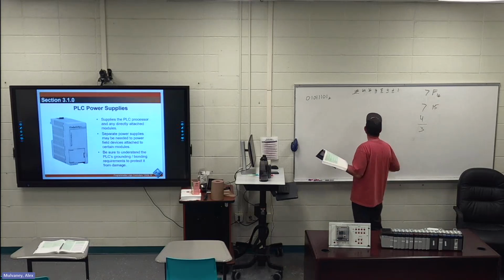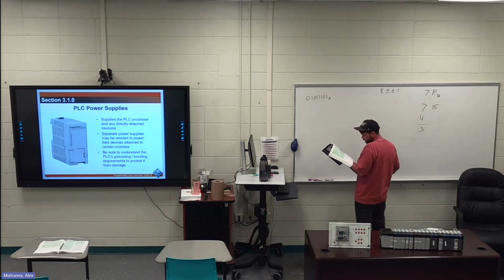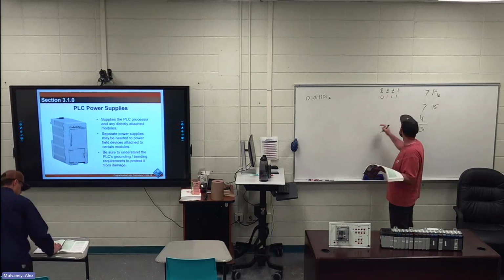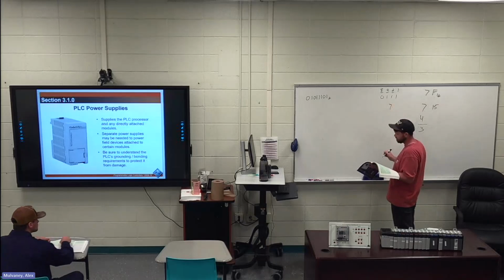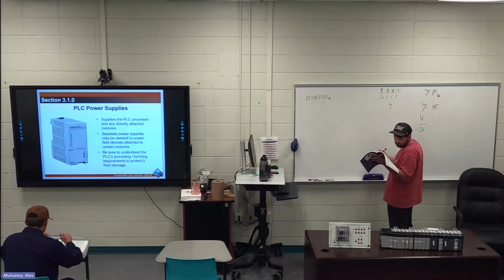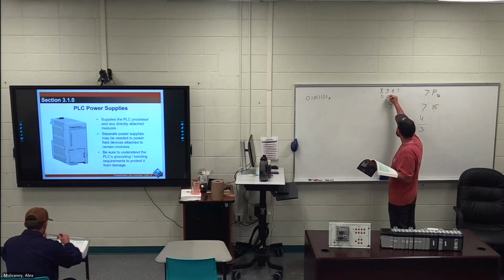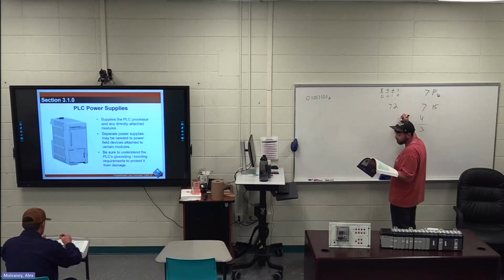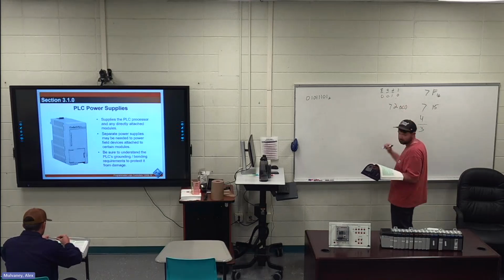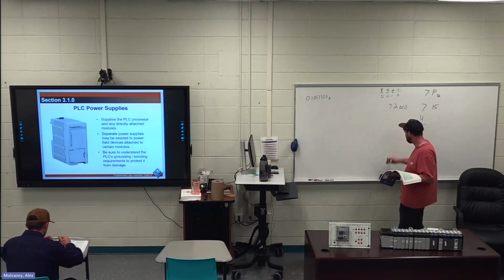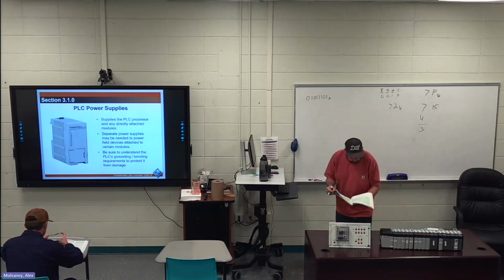So now I'm just using these. My first BCD number is 0, 1, 1, 1. We just did that. That's a 7, right? 0, 1, 1, 1 is 7. So I'll have a 7, and then my second one is 0, 0, 1, 0. 0, 0, 1, 0 is what? 2. So I have 72 BCD. Everybody go with that? The answer is A, 72.